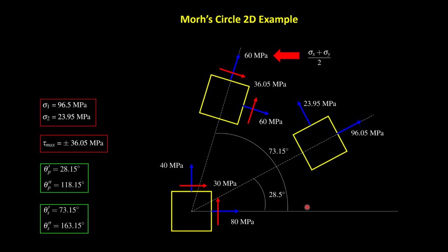Now, in this case, you find what is the load situation that doesn't help you at all. The reason we were doing all this calculation using the Mohr circle is because we wanted to know, from this state of stress, what were the maximum stresses I could find, meaning principal stresses or maximum normal stresses and maximum shear stress.